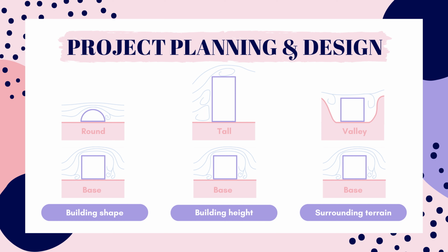This is similar to our next factor, which is terrain. If a building were sitting out in an open prairie, no trees, mountains, or other buildings in sight, then that building would have greater wind pressure than a building surrounded by trees or protected by hills.